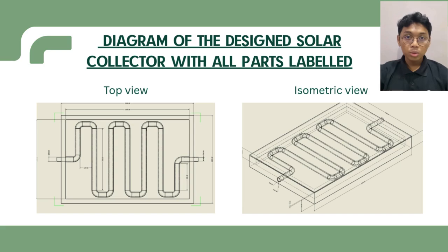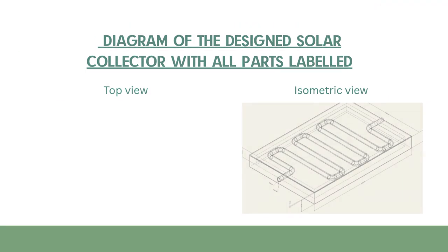and water. So the critical labels are first, transparent cover, and then second, absorber plate, third, flow tube, inlet and outlet mark. For the insulation layer, the isometric view reveals layer construction: glass cover, absorber tube assembly, and then back insulation. The final is the structure frame. So the mentioned callouts show a 20mm gap between glass and absorber for convection suppression and 75mm side insulation thickness to prevent edge conduction loss.